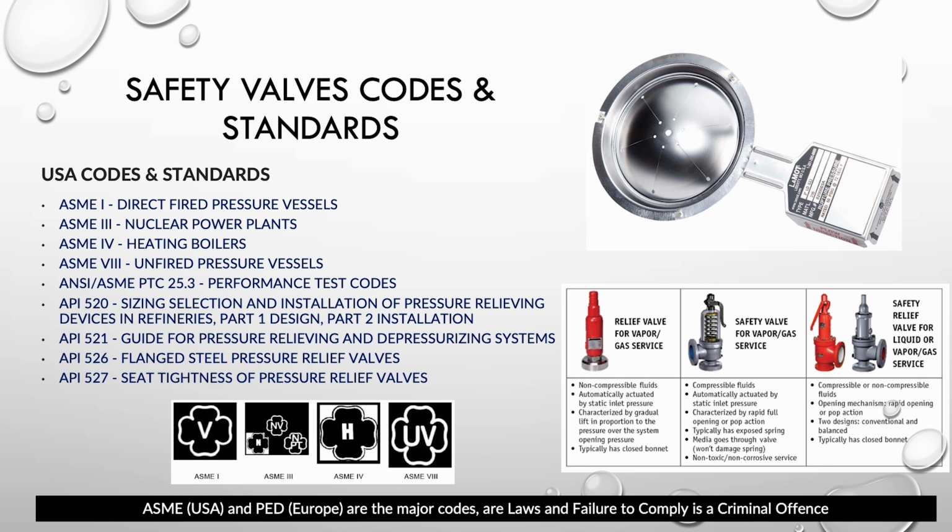But at the end of the day, it's the same concept when it comes to sizing. But again, like we have mentioned earlier, you don't need to make it harder than it should be. If we are looking at pressure relief valves, there are codes and standards to go by. And I want to be stressing that fact. The codes and standards, like for example, ASME in the United States or PED in Europe, those are laws.